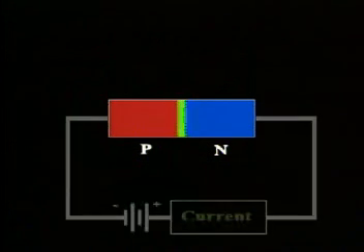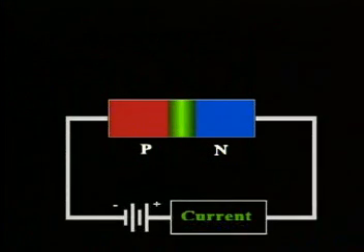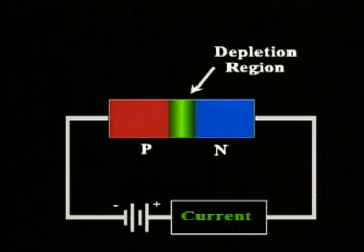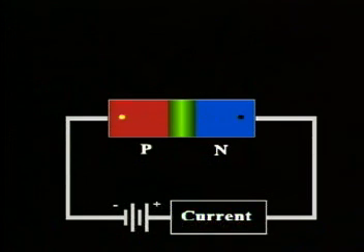First, the photodiode must be reverse biased, with negative connected to the P-type material and positive to the N-type. In this condition, no current flows in the circuit because a large depletion region forms at the junction, resisting the flow of current. If incident photons strike the device at the depletion region, the resulting electron-hole pairs separate and quickly move to their respective regions. This movement shows up as a current flow in the external circuit.